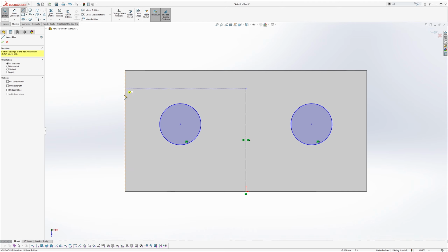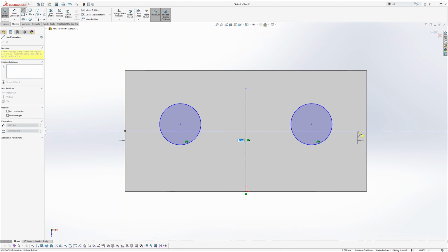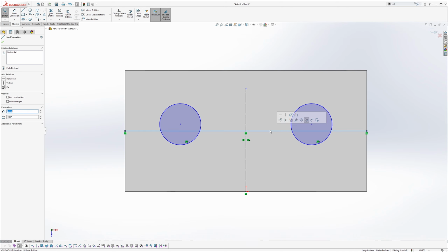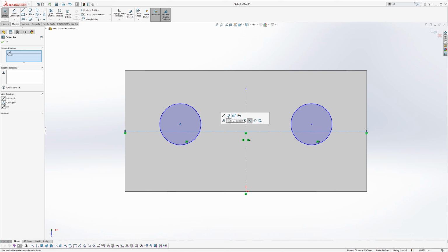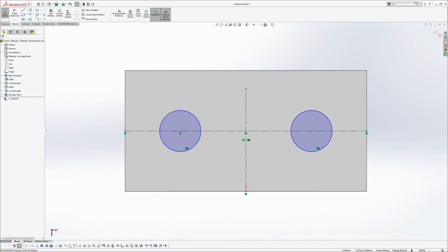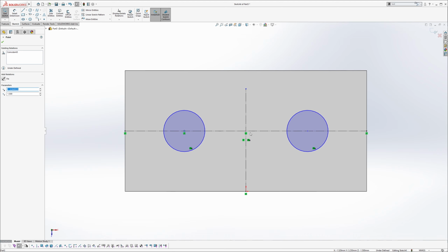So let's do that. Let's hover over this edge, create this midpoint, go over to this side, connect it, hit exit, make this construction, grab this node, select this, and just make this coincidence. Okay, now we have it on this. Now it's center from both directions.